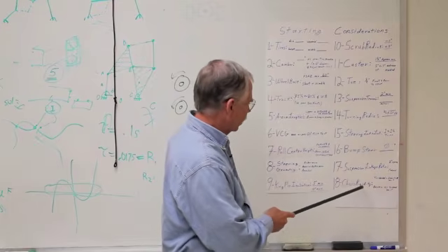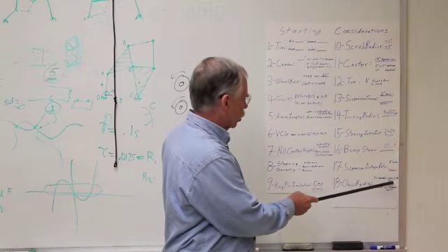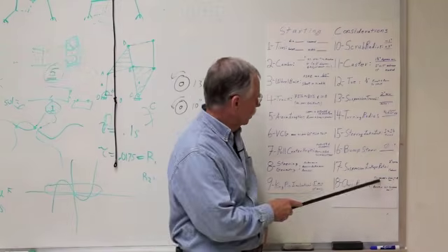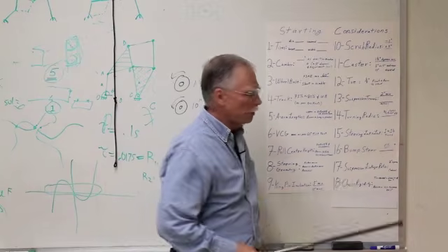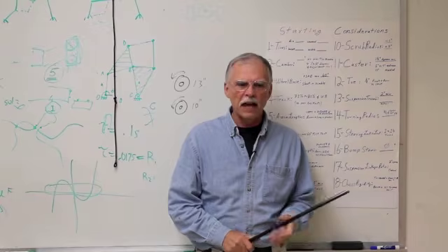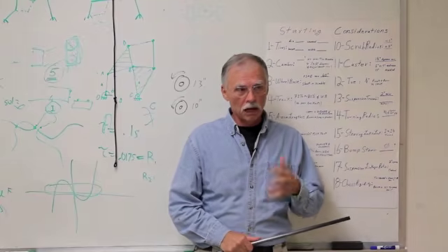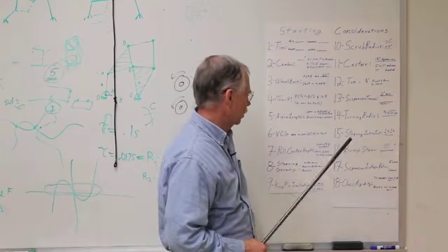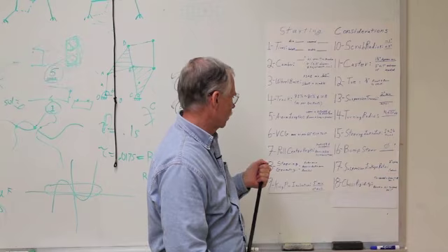18, chassis rigidity. This is what I think is a good chassis for a tube chassis. Torsional rigidity, if it's 2,000 foot-pounds per degree, I think that's good. It's not as good as possible, but it is very, very good for a student design car to have 2,000 foot-pounds per degree of chassis rigidity.